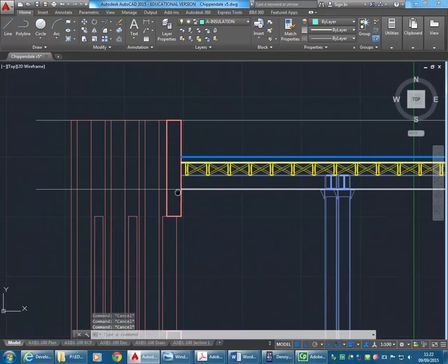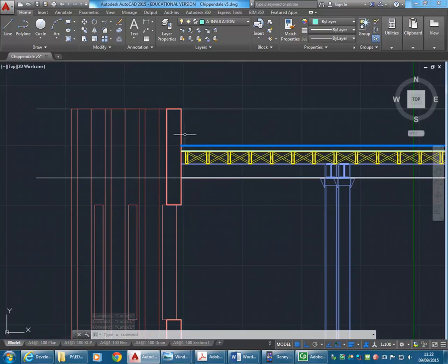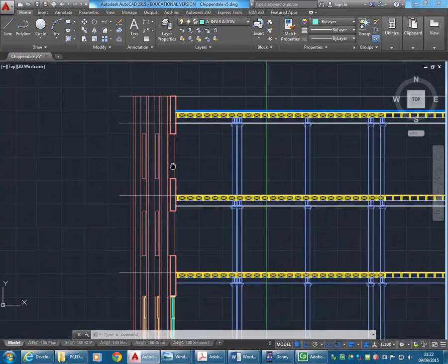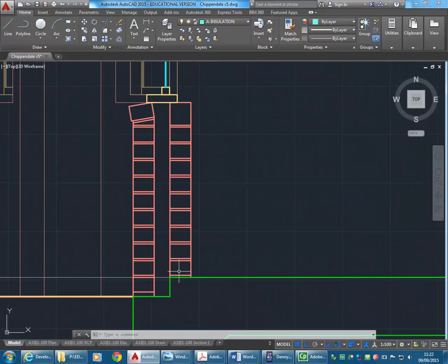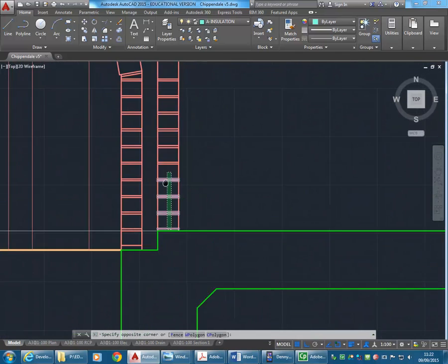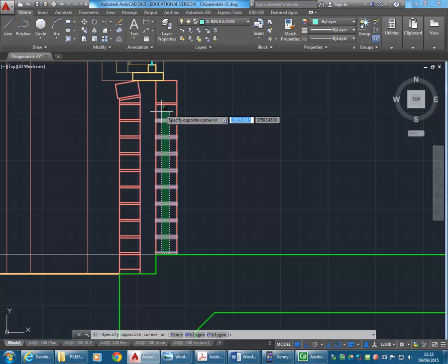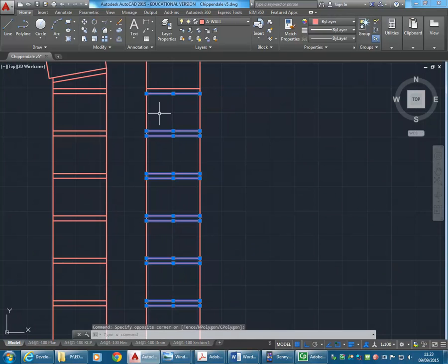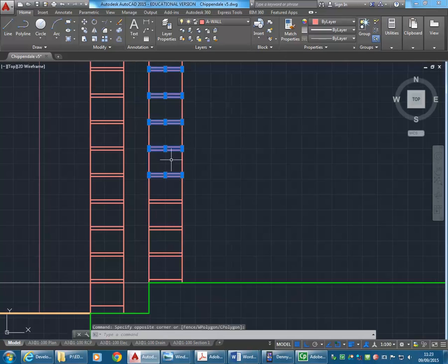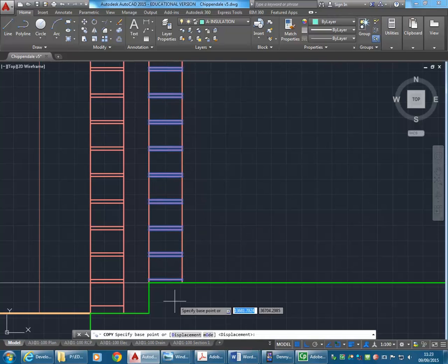And so it wouldn't hurt to have some bricks there to get the flashing right. So once you've drawn some bricks anywhere else, you can easily copy them up. Yes, I noticed here, because I zoomed in while I was selecting it, I missed out the bottom. They're 86. You can do them 85, but 86 I've done because it just works out better.